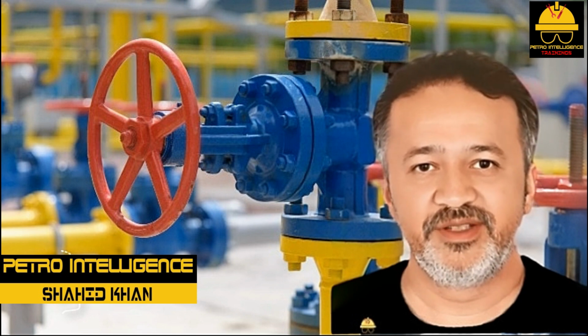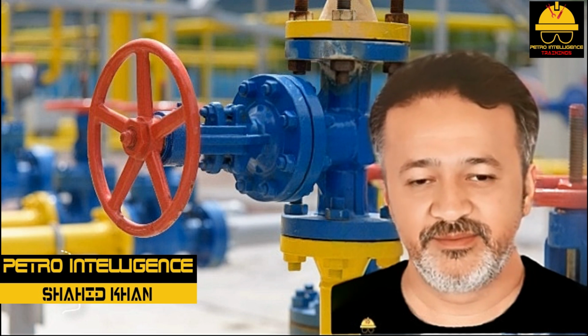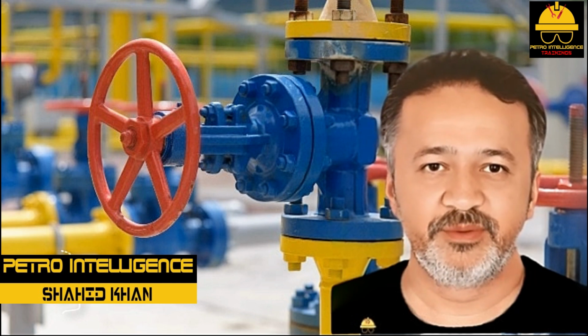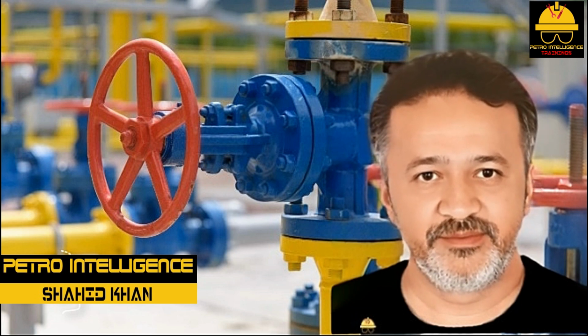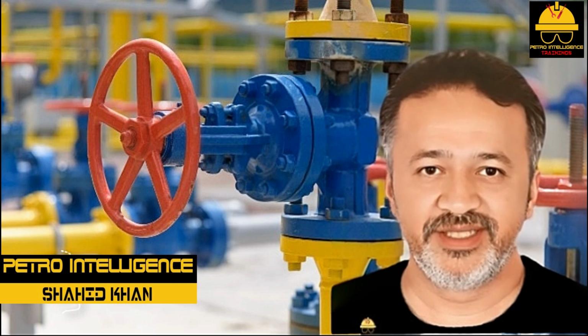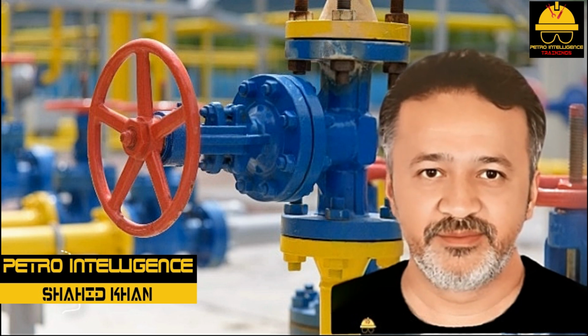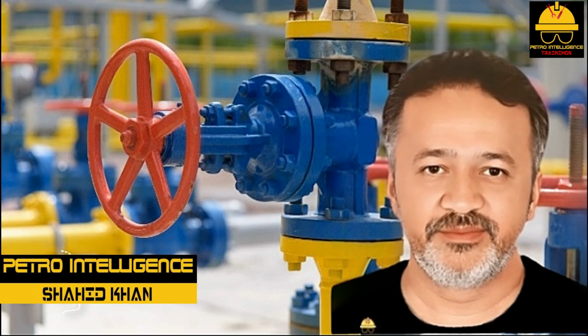A butterfly valve has a pivoting flow control element shaped like a flat disc. Diaphragm valves use a flexible membrane to throttle sticky, viscous, or corrosive materials. Relief valves automatically respond to sudden increases in pressure in liquid services. Safety valves do the same thing in gas services.